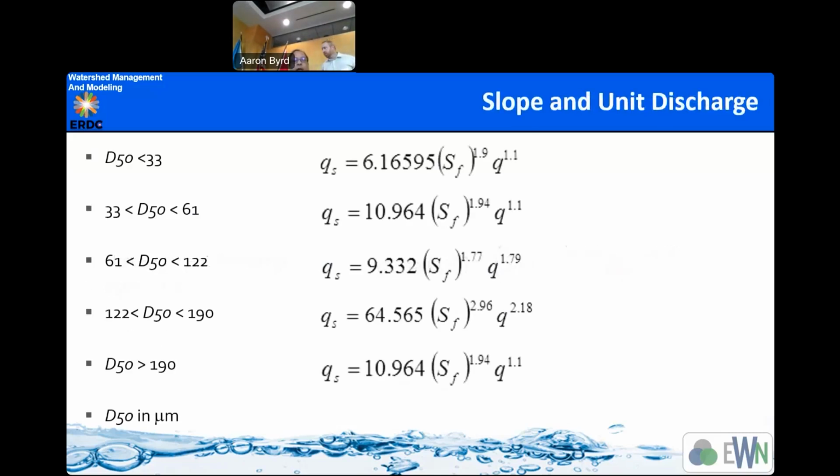So again here, these are defined in terms of the energy, right? The energy is the flux and the slope. But here, all the equations require the mean size diameter of the sediment particle, for different fractions of sediment. And all these equations within themselves define the parametric values and everything that depends on the median size diameter.